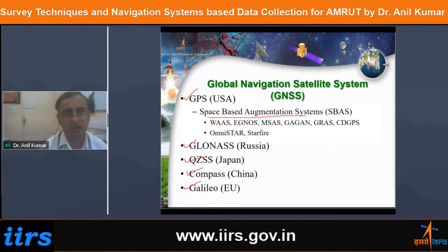If we have one GPS receiver and we want the accuracy of that receiver to go from 4 meter to 1 meter, we can use SBAS, satellite-based augmentation system, and in different countries it is known by different names. Like for USA it is WAAS, EGNOS for Europe, MSAS for Japan, GAGAN for India, and then a few more from African and other areas for augmentation purposes.